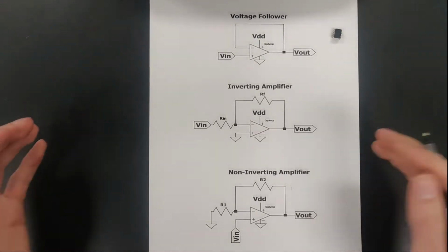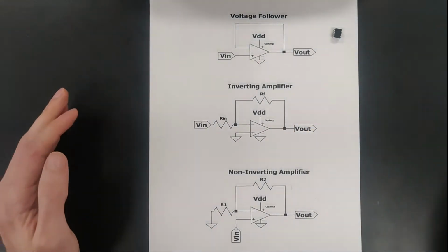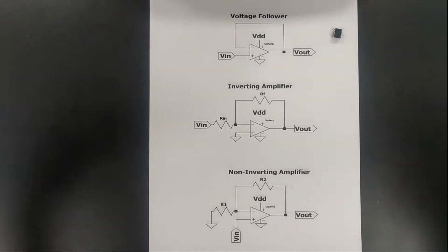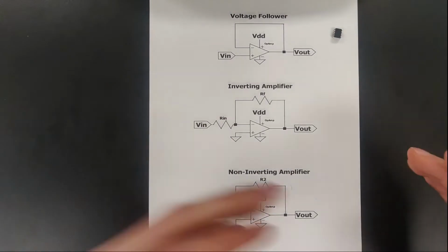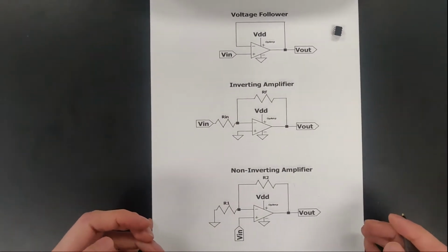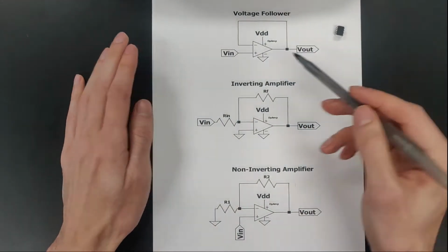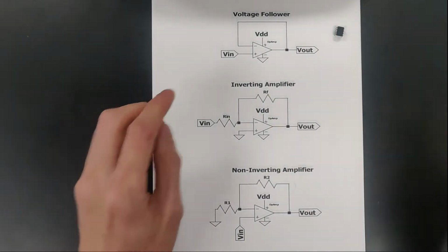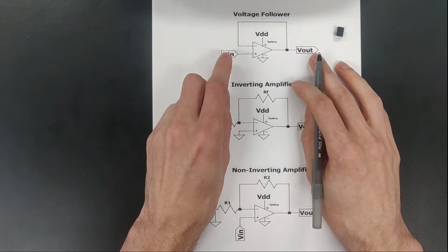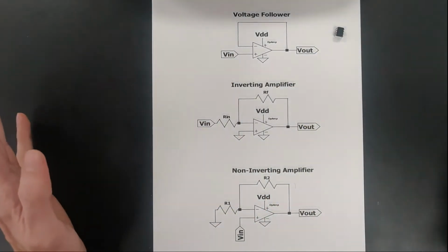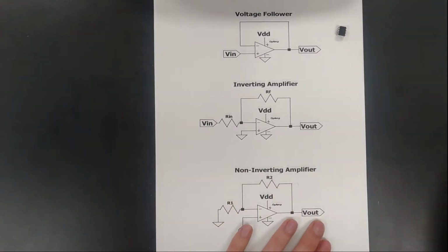So yes, what's the point of a circuit that just takes something in and you get the same thing out? Well, op amps have a very high impedance, so it's used as a buffer in circuits if we're going from high current and we want to transfer this signal over to something else. It's a way of doing that safely, I guess. So pretty simple circuit, and we'll discuss this in the lab, but if our input and our output are going to be ideally the same, what should our gain be? And I'll let you all think about that. All right, so that's part A.